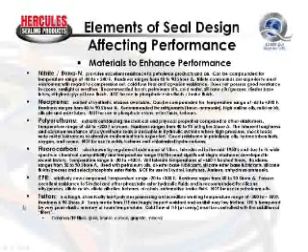Has very poor memory, however. When you go to install a Teflon seal, they're very difficult to install because they'll stretch and they do not want to come back to shape. So if you heat the seal slightly, as outlined in our seal catalog, it'll make it easier to install, and then put some type of constriction around it, like a wear ring, and clamp the wear ring down very carefully so as not to damage the surface. And as the Teflon material cools, it will shrink back to size and make it easier to install.